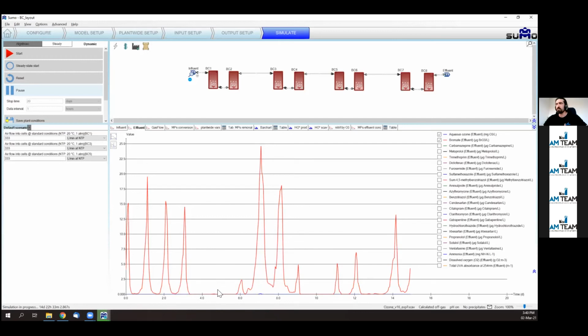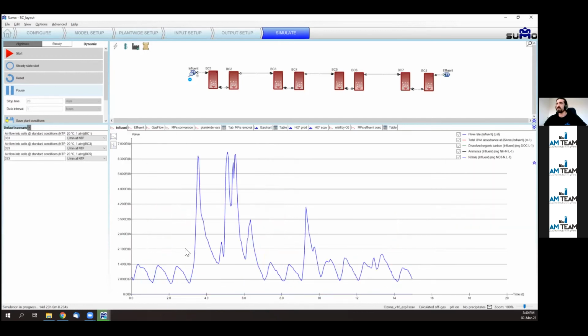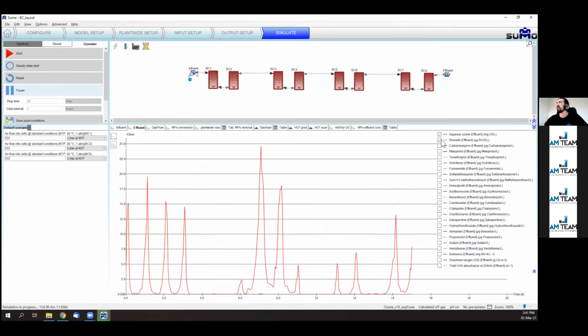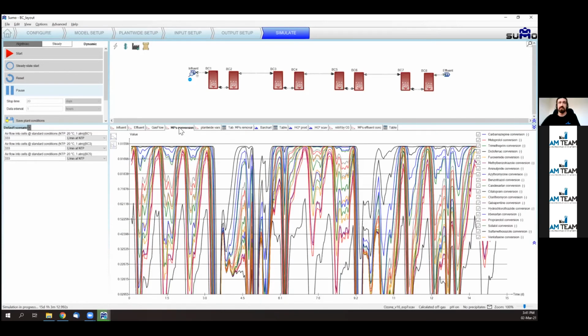And what happens in the deeps? In the deeps, sometimes the presence of ammonia helps knock down the bromate formation, as Wim anticipated. But sometimes the sole presence of ammonia is not enough, because the matrix composition does not make the life of ozone and radicals short enough. And then having residuals for a sufficiently long time in your installation makes the bromate form.